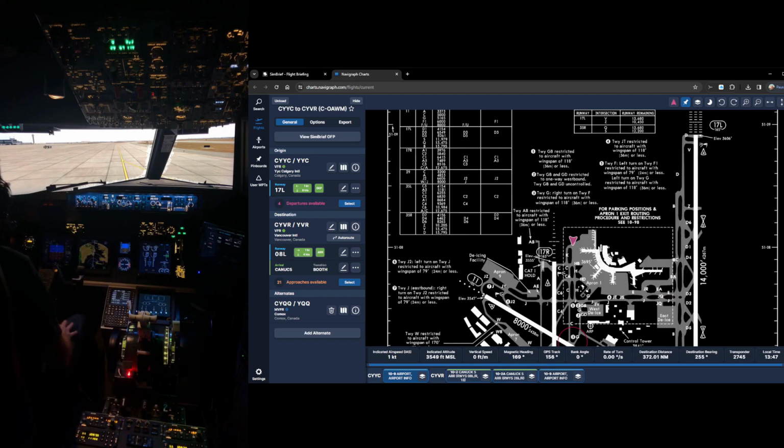Okay, so now we need to check our flight instruments, control column, and the rudder pedals. So left, right, forward, back. Good movement. Testing the rudder. Left, right. All good. Blank the lower display for flight, and we're good to taxi.